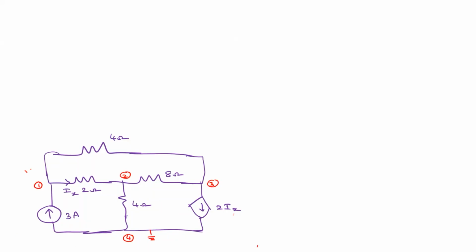So assume this voltage is V1, this is V2, and this is V3. KCL on V1. So at this node, the first thing we need to apply is KCL. This current direction is already given. So this is the one incoming current. We normally assume all the elements carry outgoing current. So this current Ix is already given, right?